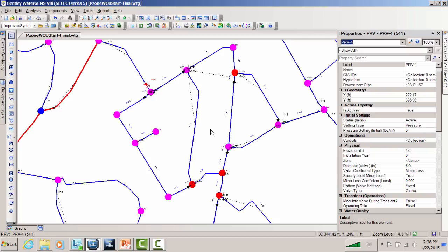In the past, the hydraulic grade in this area has been around 210 feet, and we want to lower it to a more reasonable hydraulic grade, so let's set it to about 170. You want to make the steps between pressure zones significant. You don't just want to have a PRV reducing the pressure by 2 or 3 psi. It's really not worth it.